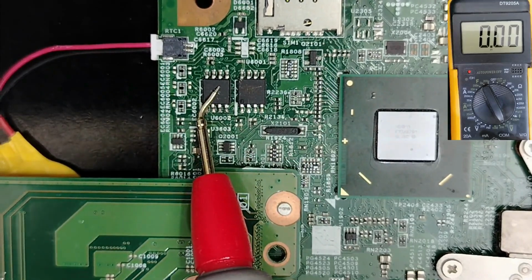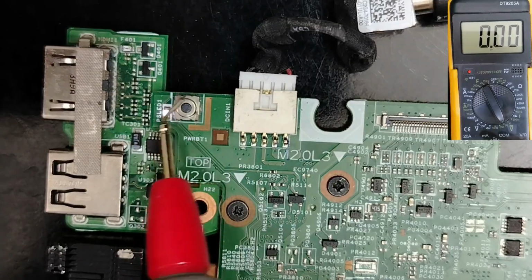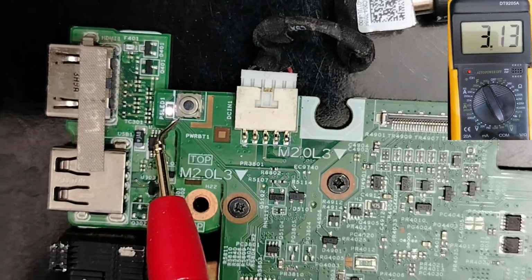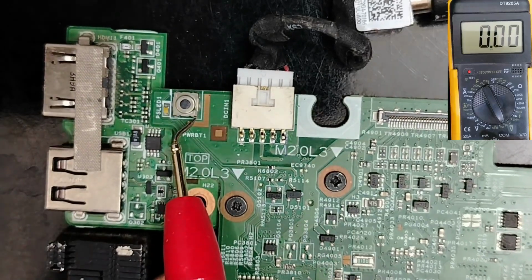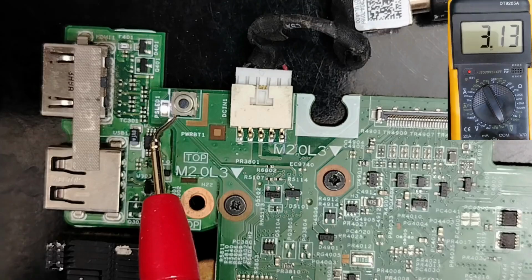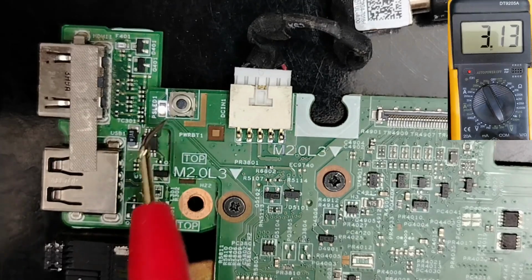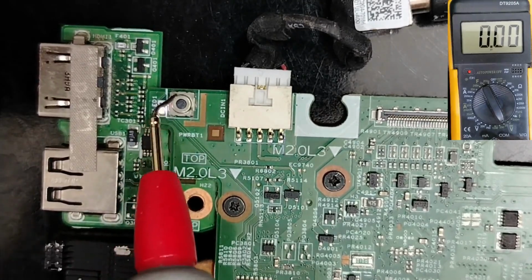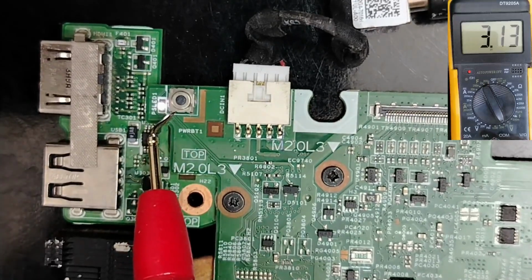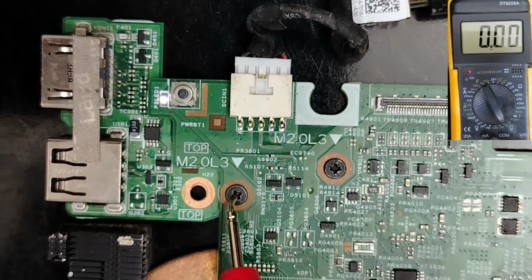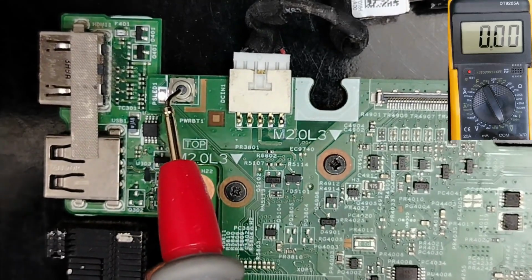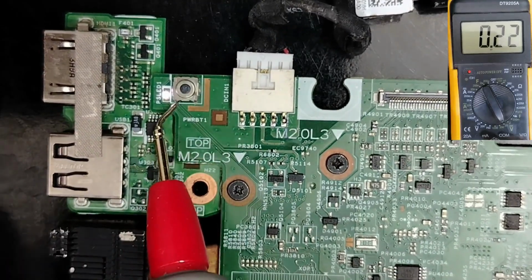So step 7, what we have to check, the power button. Do you see, guys? This is the power button. If we check, let's check this side, we have 3.3 volt on this side, and on this side we have 0 volt. This side is connected to the ground, and this side we have 3.3 volts. So please, many technicians ignore the power switch. If you have a failed, shorted switch, it means the 3.3 volt will always be in touch with the ground, which means you will get a dead board, guys. Okay, so please pay attention also to this power button and how this power button works.